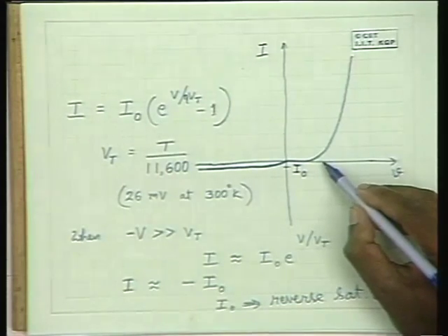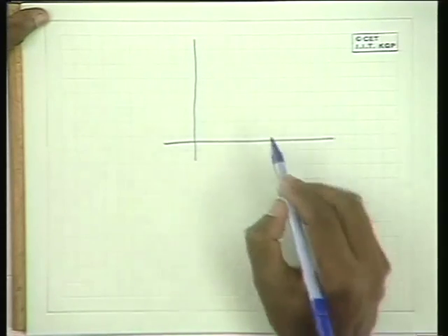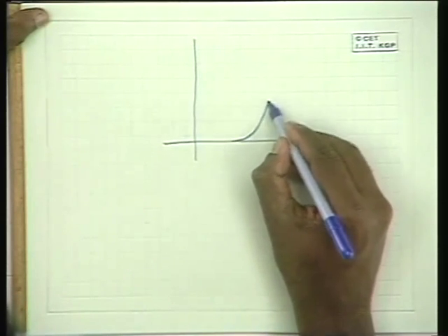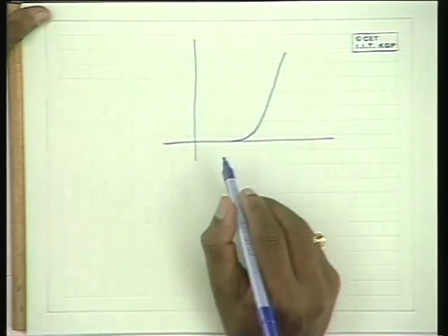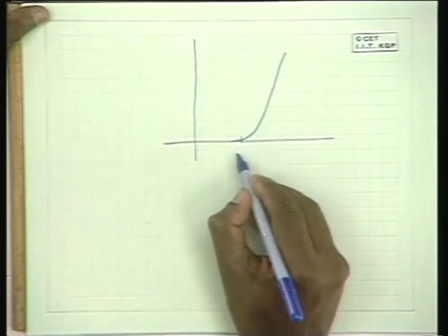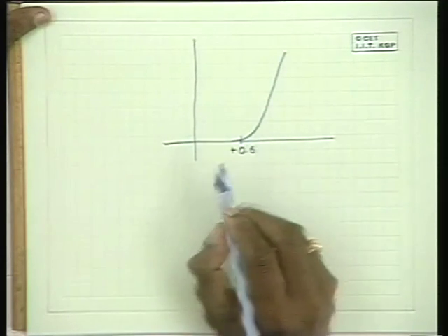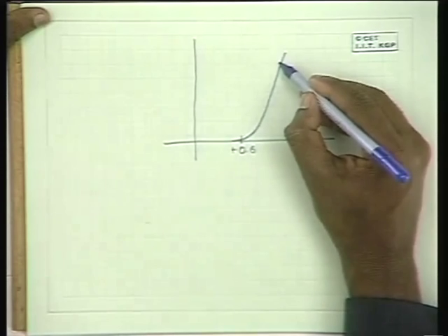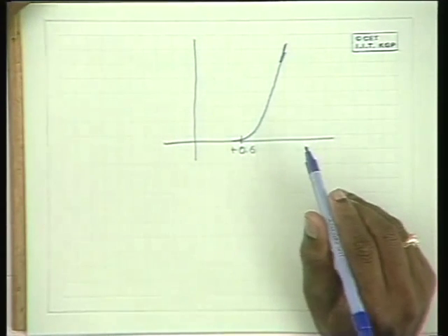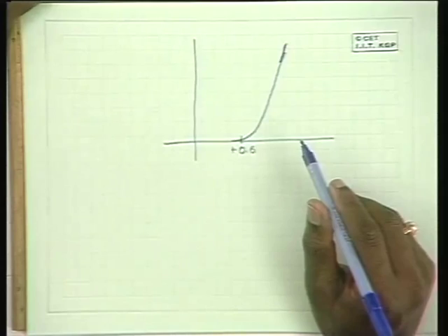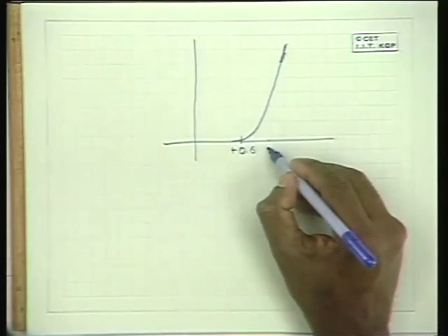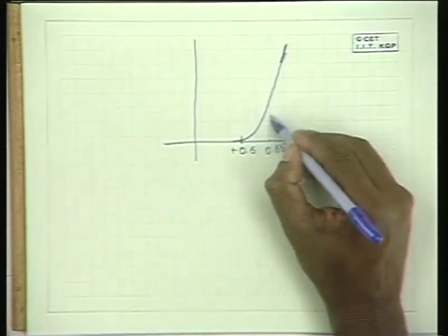Now, if you consider silicon, you will find that the volt ampere characteristics on the positive side is like this. The current is almost 0 and very small, below about 0.6 volts, and above 0.6 volts it rises exponentially with appreciable amount of current. So by the time it is about 0.65 volts, you will have a huge current flowing.